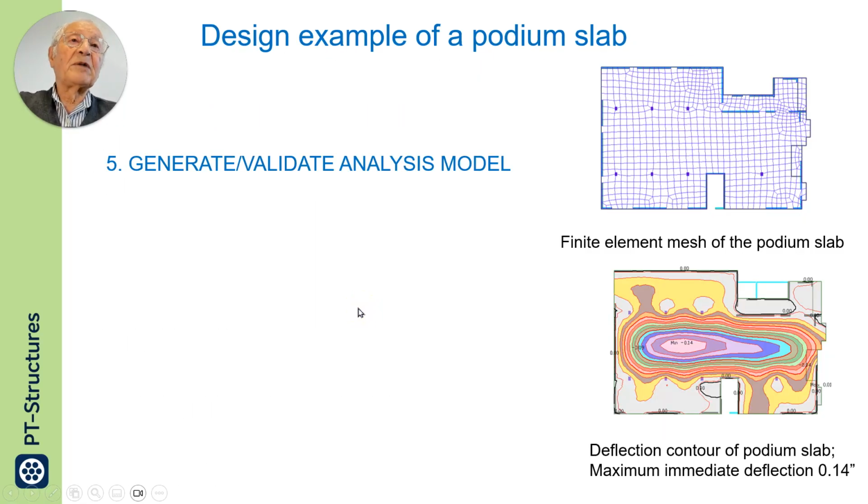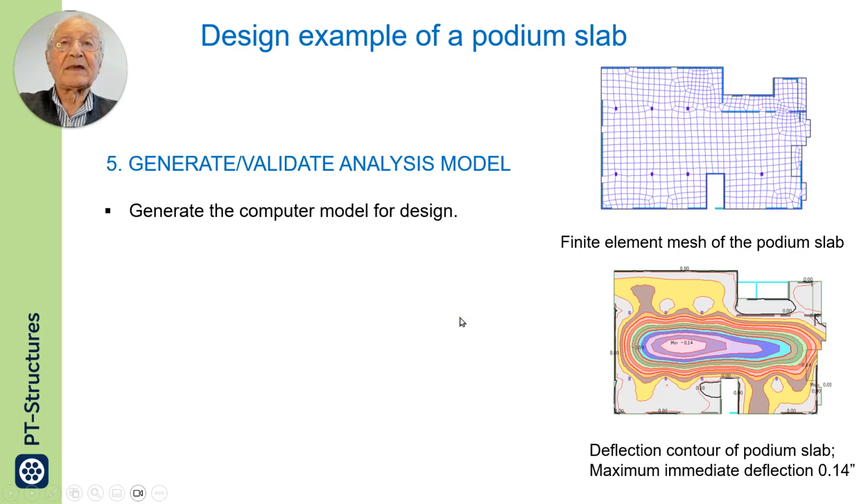Next, I generate a model. I use a finite element program. This one has a good, well-proportioned mesh, and I obtained the deflection under self-weight deflection.